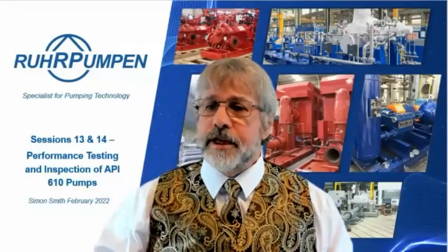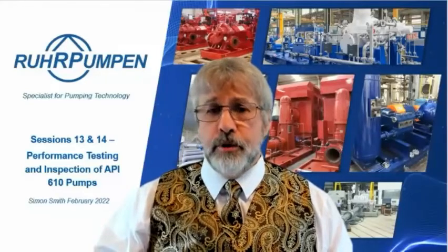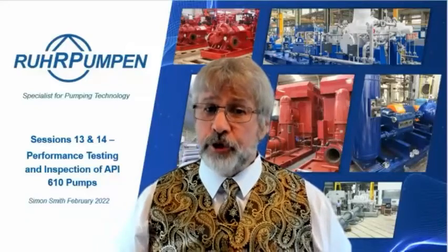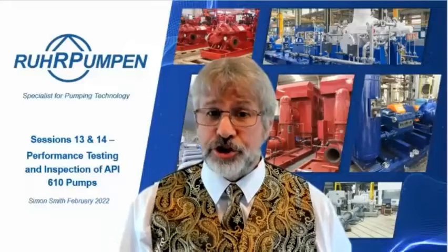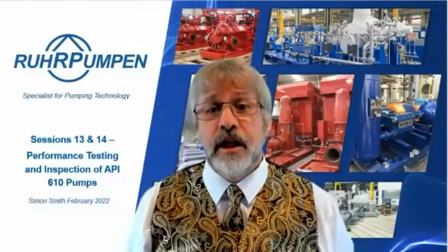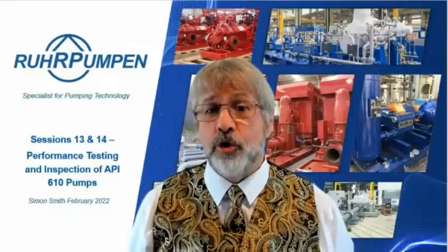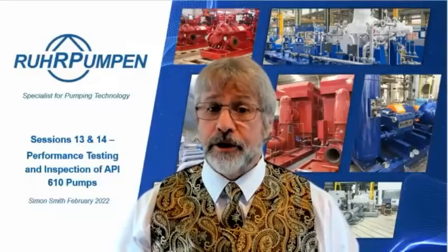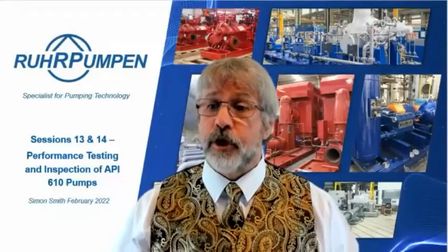Performance test is done at 6 or 9 points as applicable. Complete unit test is done at which test point? That will be for you to determine. It might be, for example, if you're doing a complete unit test on a pump that is designed for low SG, 0.7, the motor is probably not sized for being able to do that test on water, because the complete unit test will be being done on water. So under those circumstances, you might have to agree that it will be done at, say, the minimum continuous flow.